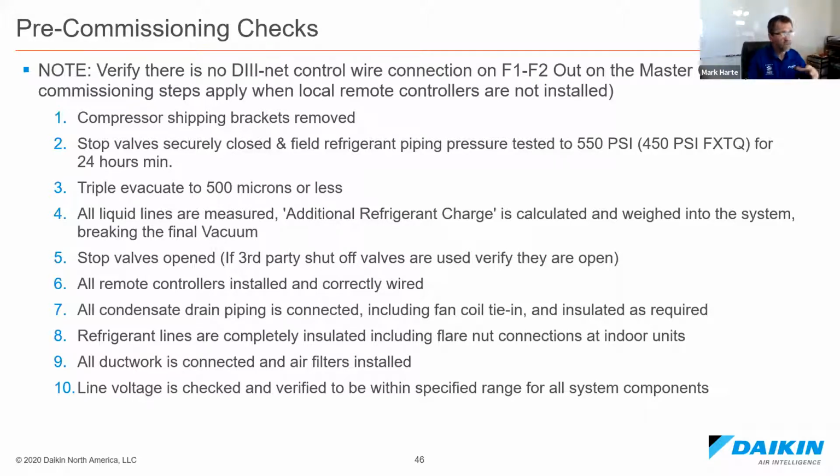All liquid lines are measured. In the class, we teach guys you can calculate the additional charge, because you're always adding charge to a VRV system. It depends on the length of your liquid line, and there are a couple other parameters. The install manual that comes with the outdoor unit tells you exactly how to calculate the additional charge. But the Web Express program, once you fill it in and put in all the pipe lengths, will tell you what your additional charge is.